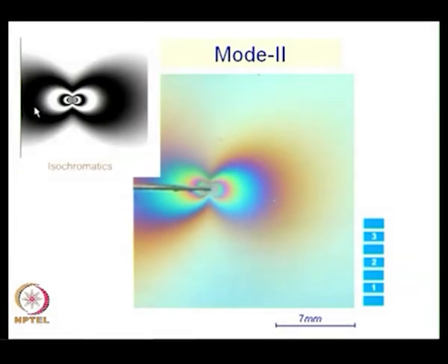See, in photoelasticity, if you use a monochromatic light source, I would only see black and white fringes. If I use a white light source, which is a multi wavelength source, then I will see fringes of different color. So, do not confuse that experimental fringes are colorful, Westergaard solution is black and white. So, Westergaard solution is useless. Do not make such drastic conclusions.